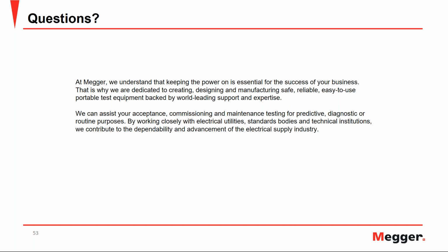Okay, so power factor testing has been a very useful tool throughout the years to diagnose the insulation of transformers and many other insulations, but especially in transformers, it has been the main tool to evaluate or diagnose the condition of the insulation.